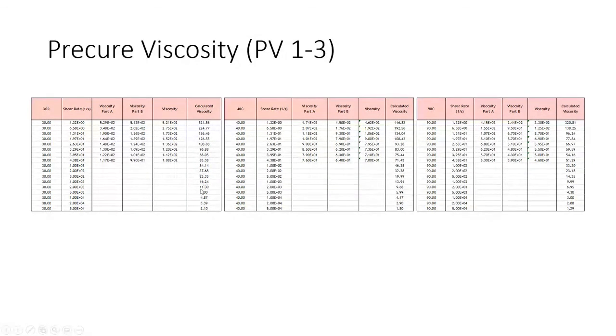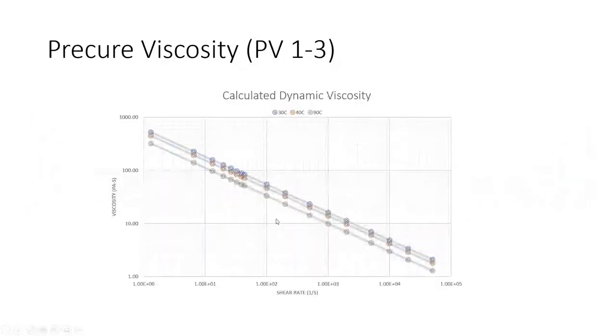And we now plot out calculated viscosity. And now we can look at it from 1 to all the way up to millions of reciprocal seconds, because we're assuming that this extrapolates, this series of data right here, this was the limit of what we could test, extrapolates all the way through the power curve down here.